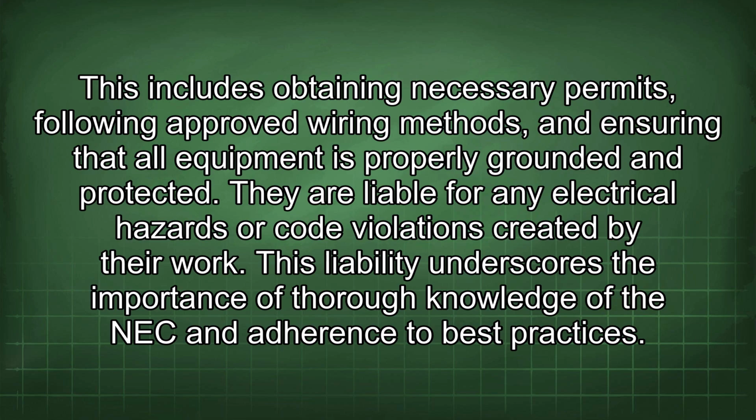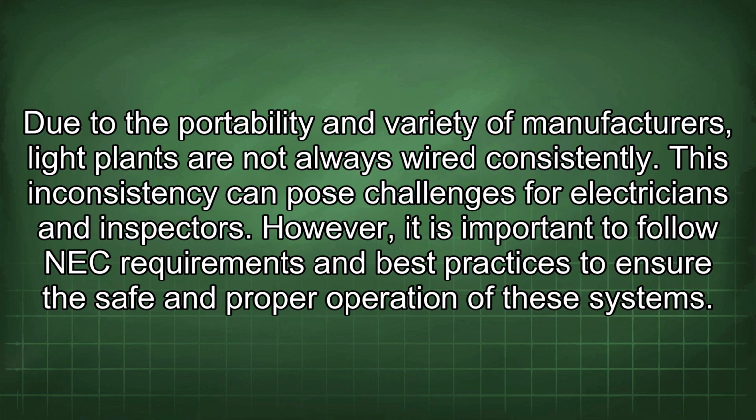They are liable for any electrical hazards or code violations created by their work. This liability underscores the importance of thorough knowledge of the NEC and adherence to best practices. Due to the portability and variety of manufacturers, light plants are not always wired consistently. This inconsistency can pose challenges for electricians and inspectors.